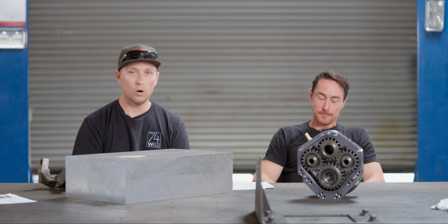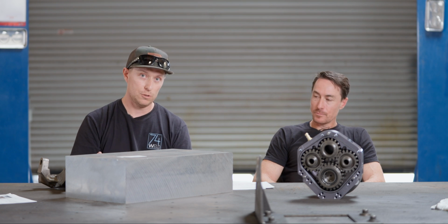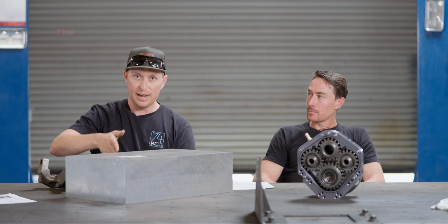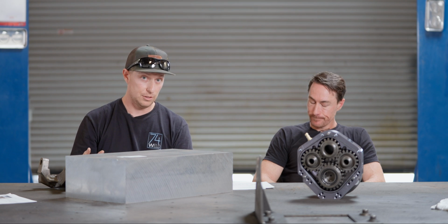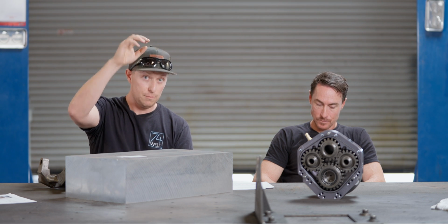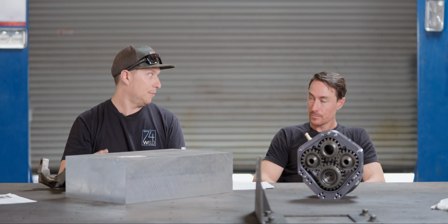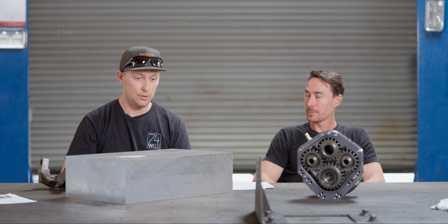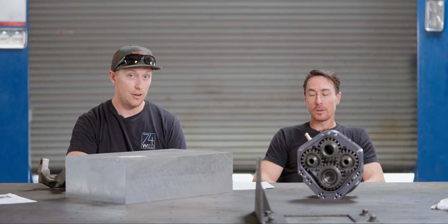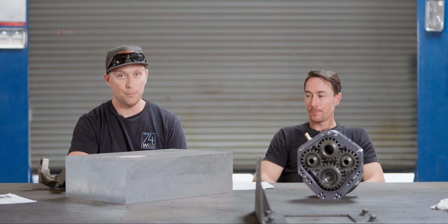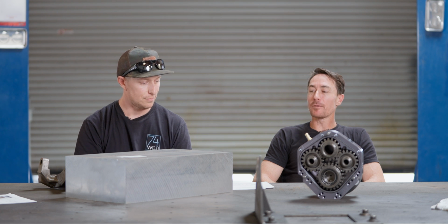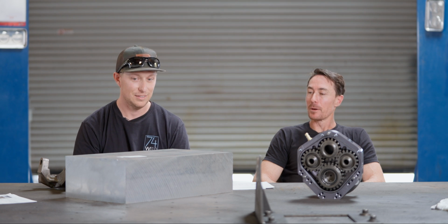Talk about work hardening. When we're talking about going from the elastic to the plastic region, then coming back over, like we were discussing before, now you've effectively raised your yield strength. So work hardening, again, more nuance, isn't always a bad thing. When you roll out material from a mill, you're strengthening it, you're strain hardening it, and that could be a desirable thing.